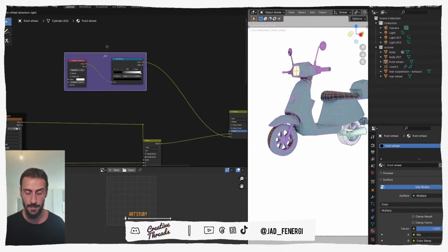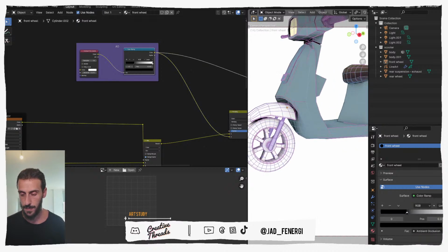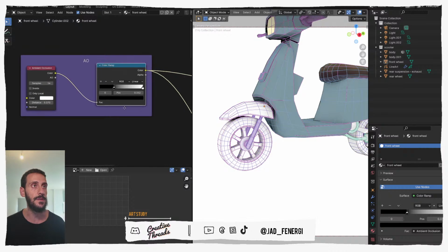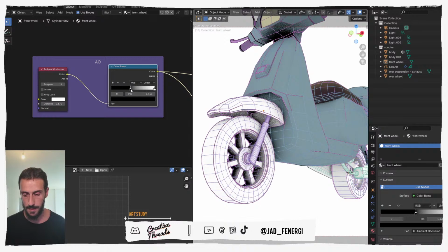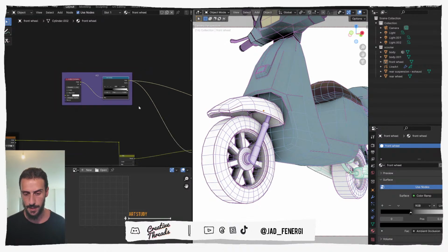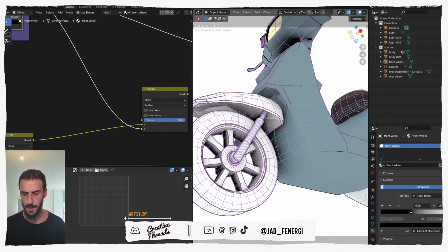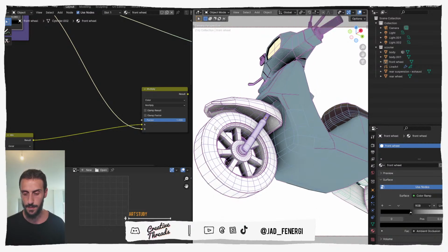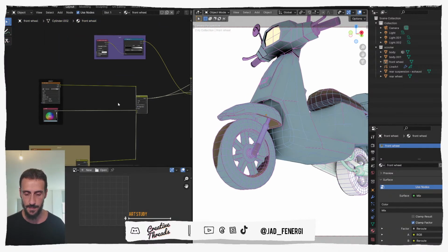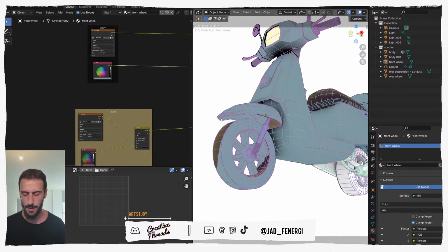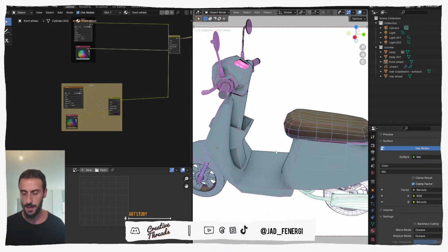So what's happening here? We have an ambient occlusion layer. So if you just check it out by itself in here, I'm gonna try to zoom in so you guys can see. So that's like a mask, or I'm not using it as a mask yet. I'm using it just as a mix or multiply on top of everything. So this black part is added to, or multiplied to the base colors, and then you have this mix node that mixes two different colors with each other. Which for this piece, it's the seat versus the body parts.